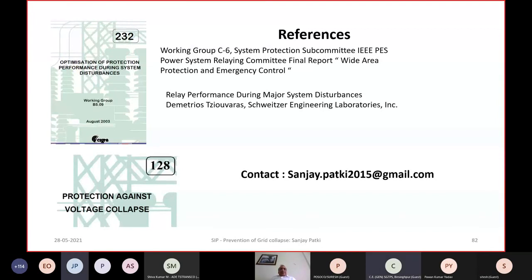And if there is a tertiary loading also, then HV side and LV side currents both can be monitored. If there is no loaded tertiary, it's only a 2-winding transformer, then overload can be monitored only on one side.